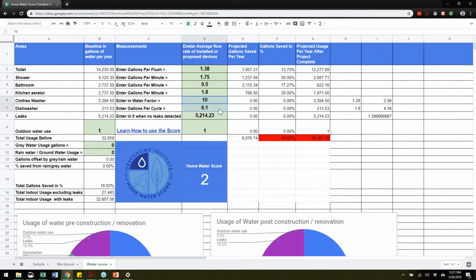And I do want to make a note on these because a lot of times you might walk away from the project with the client not having a clothes washer yet, or maybe this is a spec build and the clients have to supply their own clothes washer. In that case, you're just going to have to assume the worst, that they're not going to be getting an Energy Star clothes washer, unless there's some kind of incentive in the area that behooves people to always do this, and you can show us some data that they always do. We're willing to accept that. That's great. But until then, you're going to make a worst case scenario assumption on the clothes washer, assuming you walk away from the house and don't hand this off to the client to finish it.